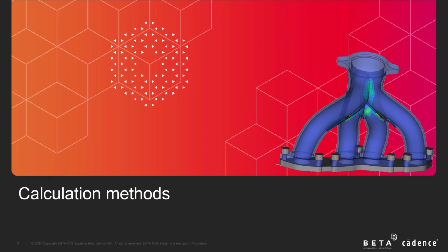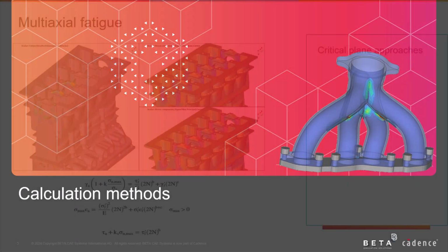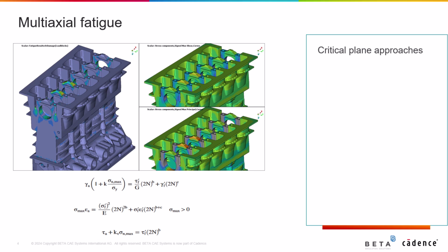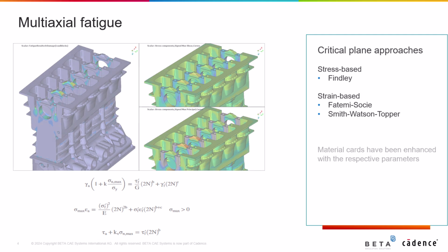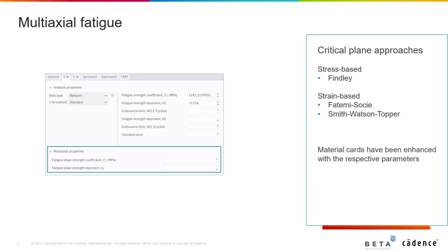Let's start with the new calculation methods. Several critical plane fatigue life estimation models have been suggested. The models can be divided between stress-based and strain-based. For stress-based multi-axial fatigue, we support the Findley model. For strain-based multi-axial fatigue, we support the Fatemi-Socie and Smith-Watson-Topper models. Also, the material cards have been enhanced with the respective parameters.